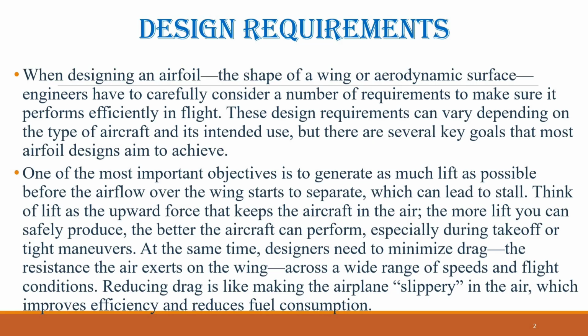Recently, there has been a lot of interest in designing airfoils for drones and other small unmanned aerial vehicles that operate at very low speeds. These aircraft encounter low Reynolds numbers, a measure of the ratio of inertial forces to viscous forces in the airflow, which dramatically affects how air moves over the wing. At low Reynolds numbers, the airflow behaves differently than at higher speeds, often causing lower aerodynamic efficiency.